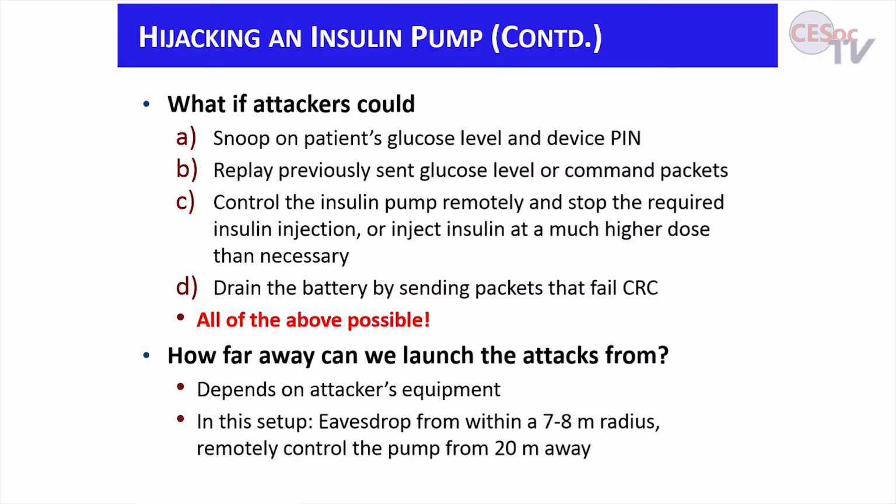You could, if it is a pacemaker, you can send a packet to it that keeps failing the CRC check, but keeps draining the battery. And changing the battery for the pacemaker typically is done every 10 years or so. So if you drain the battery of the pacemaker, now the surgery has to be done much earlier, and there's a 2% failure rate in surgery. So this draining of the battery attack is also, even though it fails, but by repeatedly doing it, you can cause malicious things to happen. All of the above are possible.